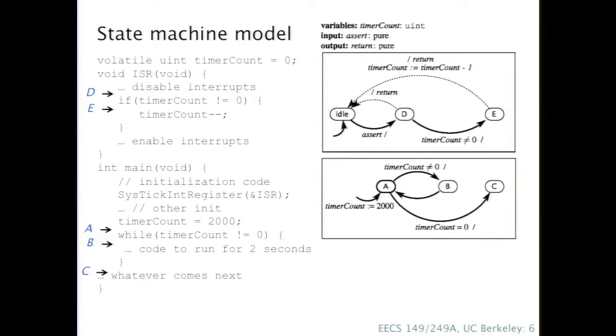Why not, Martin? Because they're not synchronous. An interrupt can happen any time. Right. They're not synchronous, so it would be really weird, and it would actually be an incorrect model of the behavior. Suppose my initial state is idle, comma A, and then when the composition reacts, both machines have to react simultaneously and instantaneously.